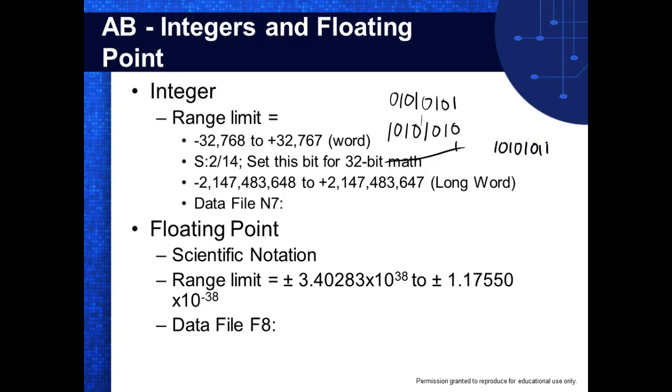So let's say, since we're using 8 bits, this would be our sign bit, so we'd say this number would be what? Negative. And this number right here would be what? Positive. So what would happen if I took a positive 85 and added it to a negative 85? 0. Let's see if that works. Of course, you have to know binary addition. So I'd go 1, 0.